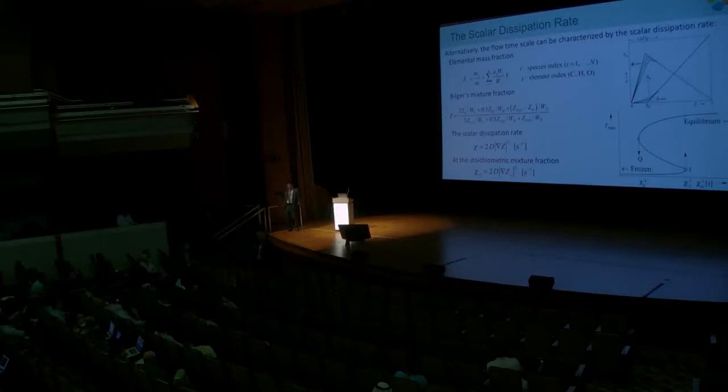Now if you want to throw in extra EGR gas recycled from an external source, this really messes up the whole thing. So if you really want to analyze that particular scenario of reintroducing EGR, you have to consider this three-stream mixture. So it is a little bit of a modeling challenge. People have come up with some ideas of how to handle that, including the Stanford group, Matthias Ihme, and there are a few other groups who have worked on these multiple, more than two streams, and this mixture fraction formulation has been extended.